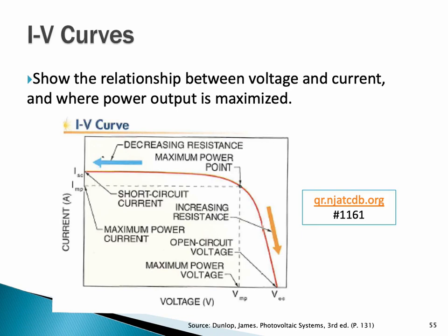But we know that we don't have ideal conditions all the time, meaning the sun is not always shining 1,000 watts per meter squared. So say we have half of that, or 500 watts per meter squared. The current line would be running across here horizontally to this point. And so then the inverter would apply more voltage, or allow more voltage into the system, so that we would be operating on this curve, further down the curve, but at its maximum power point for that given condition. This is also called the knee of the curve.